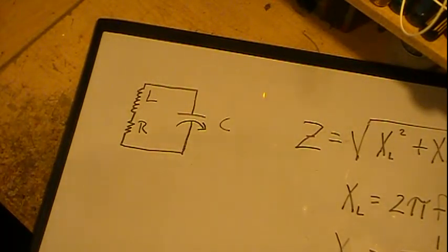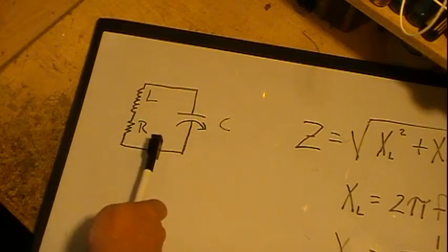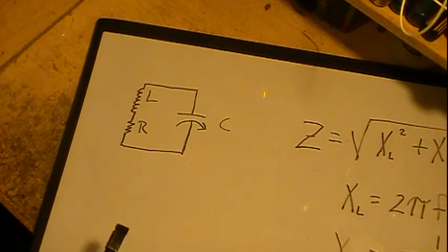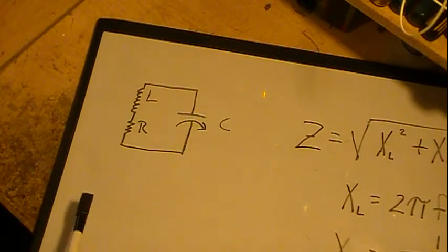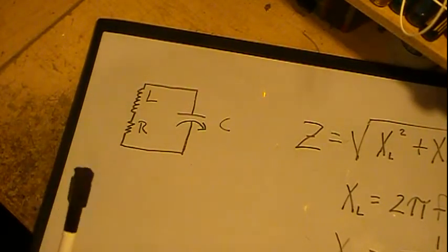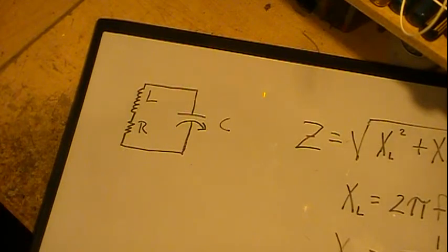So we need to express a little terminology. You have a coil in a tank circuit, say it can be your antenna coil, and there's your tuning condenser here. It could be an oscillator coil, whatever. The coil has an inherent amount of resistance in it. It's made of wire. Wire has resistance, and that's one quick way of checking a coil to make sure it's all right.